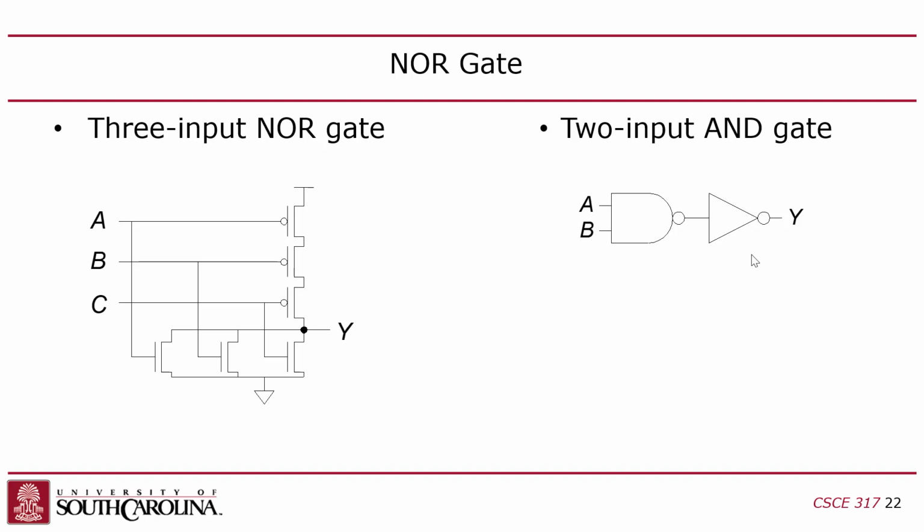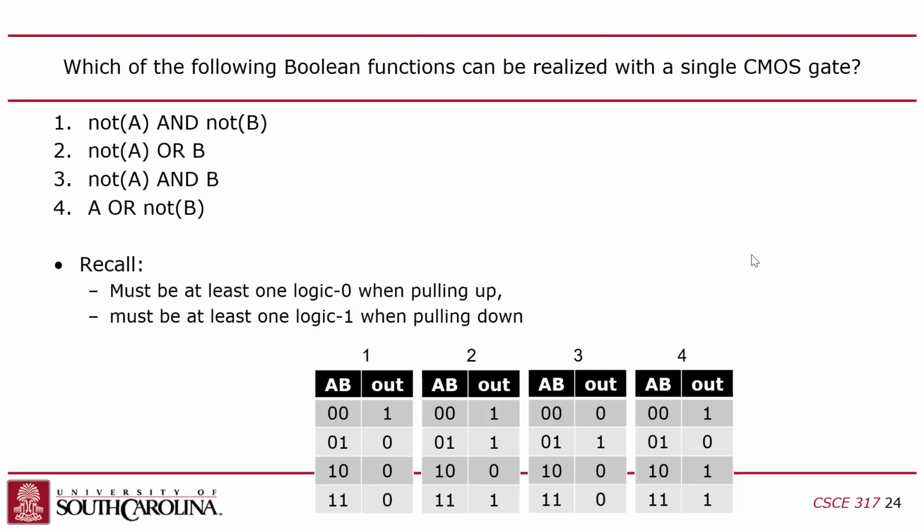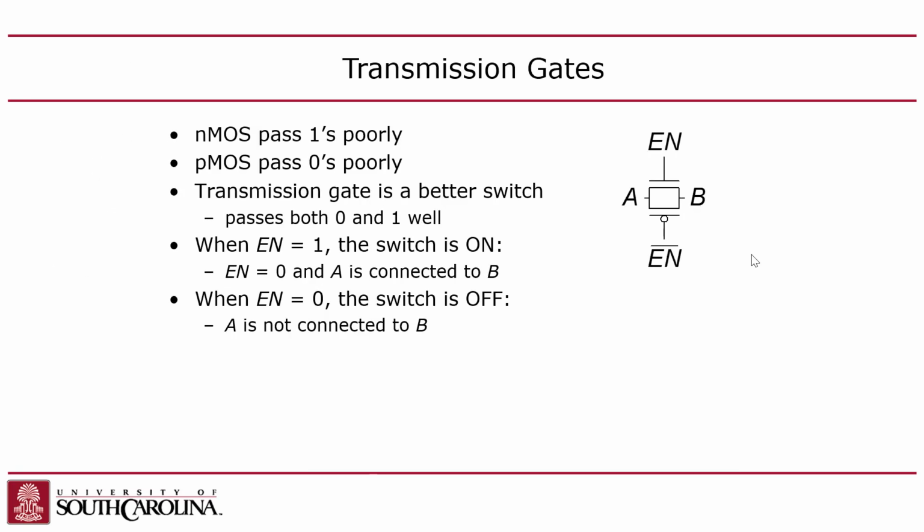But if you want to create something like a transmission gate, for instance, a transmission gate doesn't have a power or a ground in it. A transmission gate is when you have 2 transistors in parallel, which allow you to create a tri-state buffer. Basically, if you have a wire and you want to be able to disengage it from an output, or disconnect it from an output.